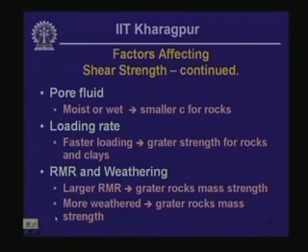Other factors that affect shear strength characteristics: presence of pore fluid. Some of the rocks exhibit smaller strength under moist or wet conditions in comparison with a dry condition. Then loading rate: if you have got a faster loading rate, generally for rocks and clays shear strength becomes greater. Then if you have got weathered rock or soils, weathered rock sample, then you are going to expect a smaller strength. If you have got a larger RMR, rock mass rating, then you would expect a greater strength of the rock mass.